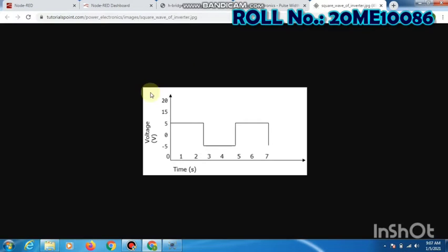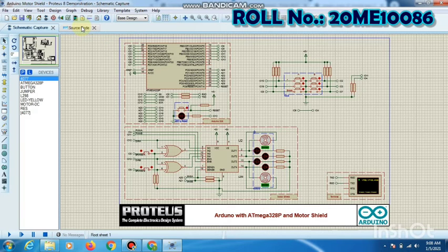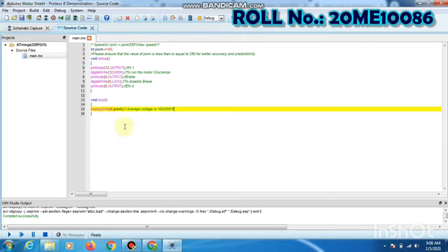Next, I am going to show you what the PWM technique is. Since the signals are only at high or low level, it helps to make an average between both of them. We switch it on for some percentage of time. For example, if we switch it on for 50%, the average would be 2.5 volts. Now I am going to show you the source code.